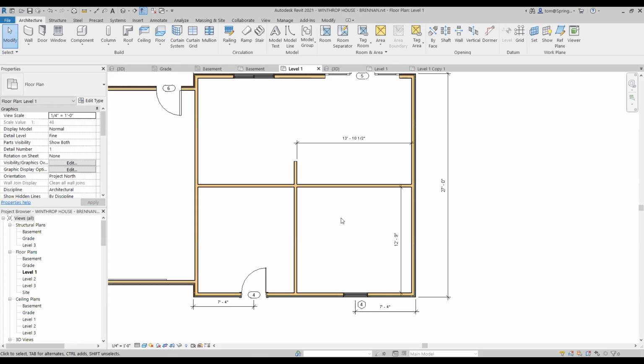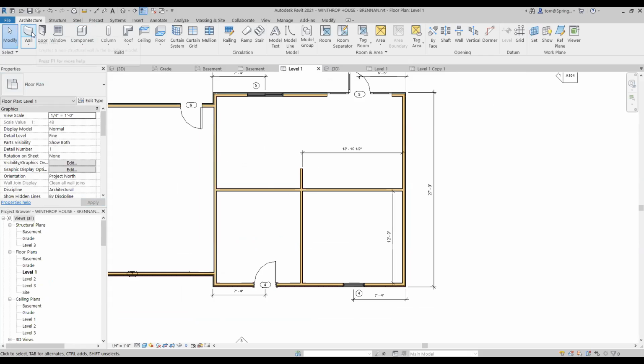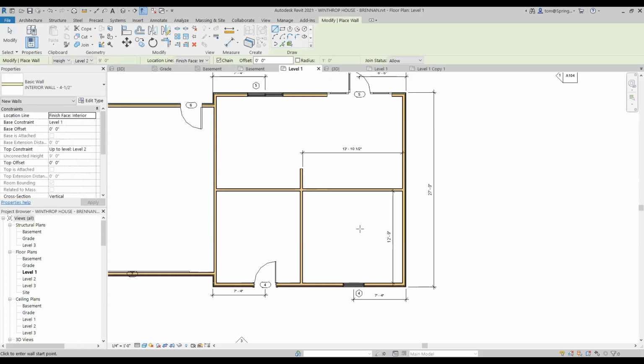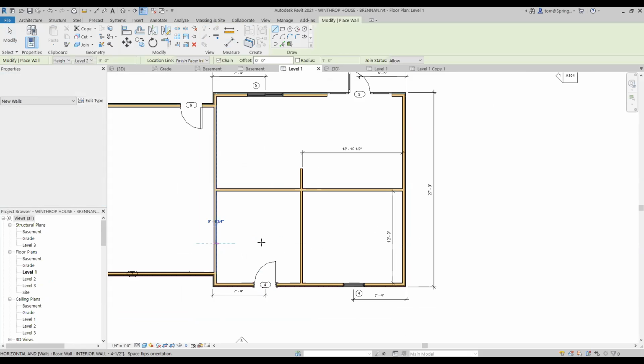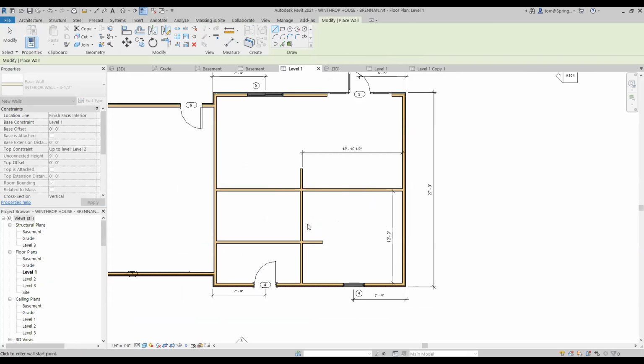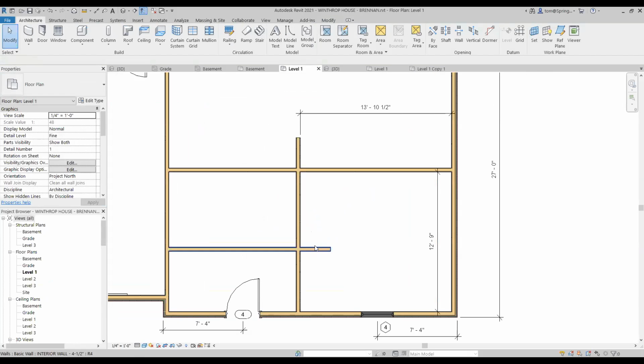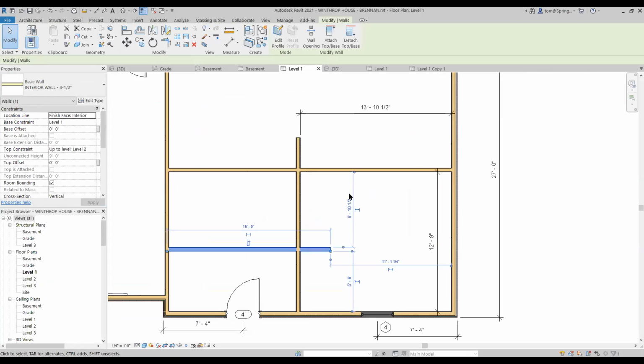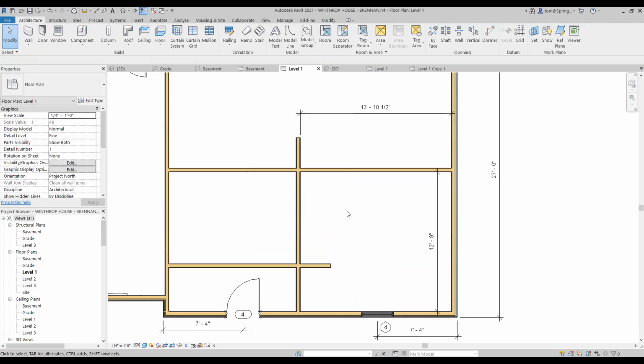To do this, I would put in another wall. You're getting the idea here that I can just use these as I need to and go like that. And then I can measure them and see how close they are. So this one is 6'10.5", and that one needs to be 8'9", and it needs to go to the other outside like this. So I'll make that 8'9". It should push it. Yeah, I went ahead and pushed it. So now we're looking pretty good.